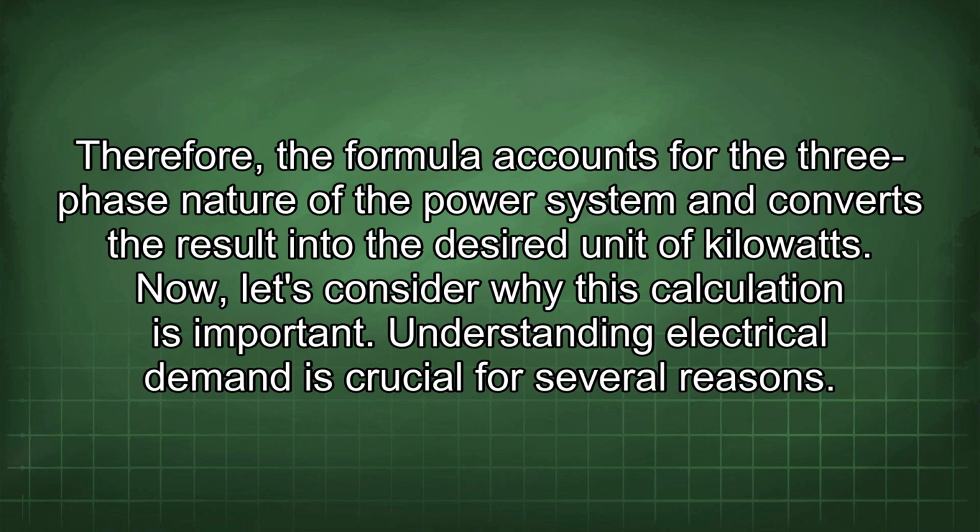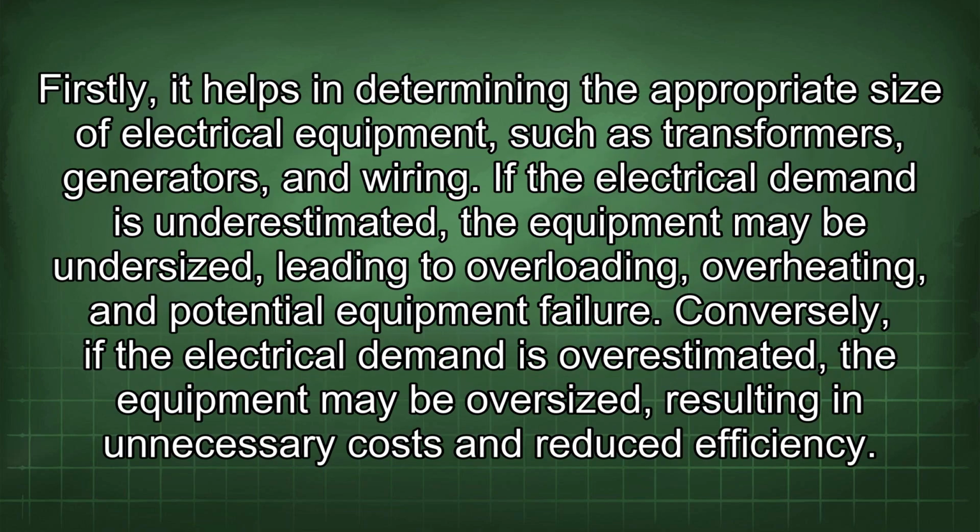of kilowatts. Now, let's consider why this calculation is important. Understanding electrical demand is crucial for several reasons. Firstly, it helps in determining the appropriate size of electrical equipment, such as transformers, generators, and wiring. If the electrical demand is underestimated, the equipment may be undersized, leading to overloading, overheating, and potential equipment failure. Conversely, if the electrical demand is overestimated, the equipment may be oversized, resulting in unnecessary costs and reduced efficiency.